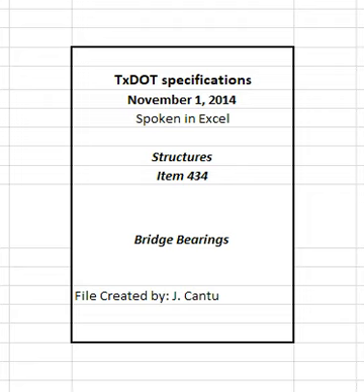Forward samples, freight prepaid, to the Construction Division, Materials and Pavements section, or their contracted testing laboratory when directed. Submit only elastomer of the type or types to be supplied. Submit pre-qualification samples consisting of 2 finished bearings typical of the formulation and workmanship for department projects. Submit 2 samples of each type when laminated and plain bearings are required. Laminated sample bearings may represent both plain bearings and laminated bearings for an elastomer formulation.